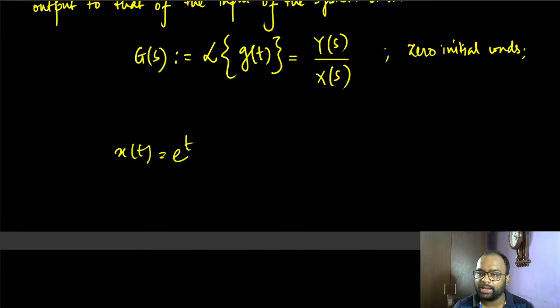For this very simple signal, there exists no Fourier transform. You cannot calculate it, because it does not exist, at least in terms of your standard functions. So there are simple functions for which the Fourier transform does not exist, and you cannot understand the sinusoidal components present in it, even if there are certain components present. The Laplace transform alleviates this restriction on the Fourier transform.